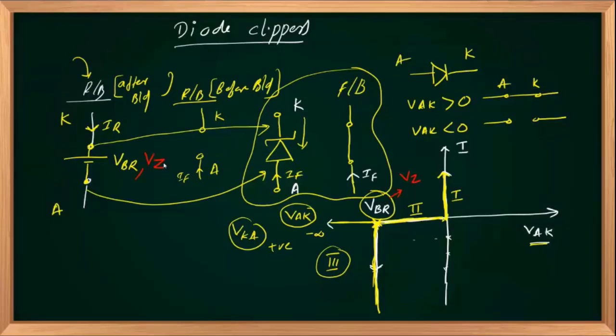And compared to our ordinary diode, if our ordinary practical diode breaks down when its PIV, peak inverse voltage, exceeds some value, once a normal diode breaks down, that diode cannot be reusable, so it will lose all of its electrical properties. So after breakdown, an ideal diode never breaks down in the reverse direction, but in the case of a practical diode, once it breaks down, you cannot use the diode for another time. It completely loses its electrical properties.